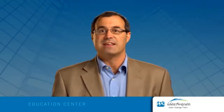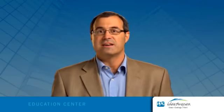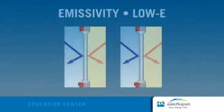All materials, including windows, radiate heat in the form of long-wave infrared energy, depending on the emissivity and temperature of their surfaces. Radiant energy is one of the important ways heat transfer occurs with windows. Reducing the emissivity of one or more of the window glass surfaces improves a window's performance and insulating properties.